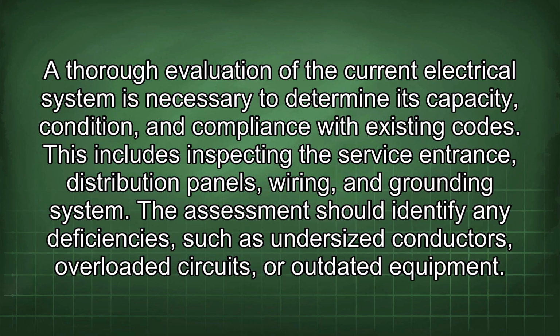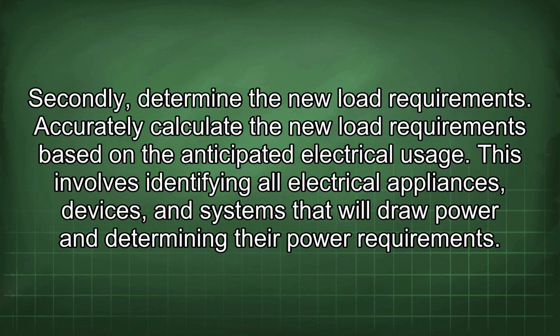This includes inspecting the service entrance, distribution panels, wiring, and grounding system. The assessment should identify any deficiencies, such as undersized conductors, overloaded circuits, or outdated equipment. Secondly, determine the new load requirements. Accurately calculate the new load requirements based on the anticipated electrical usage.